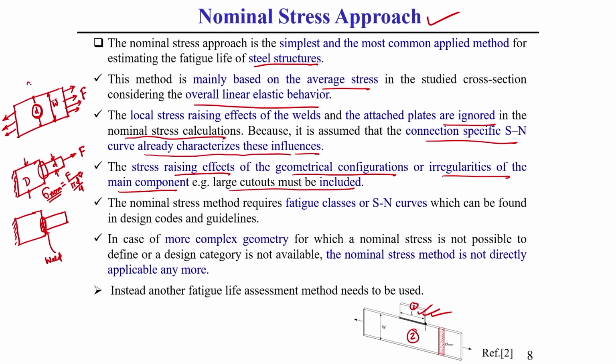For this case, once we go for calculating the nominal stress, we should consider the effect of this inner hole. So, how do we consider these things? That is generally a stress rising effect. For calculating this, the definition of nominal stress is F divided by, let us consider the thickness of the plate is T.